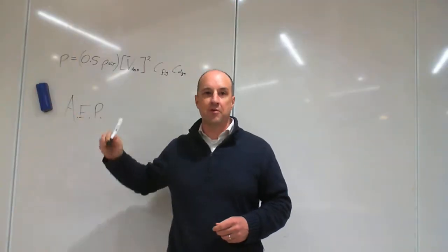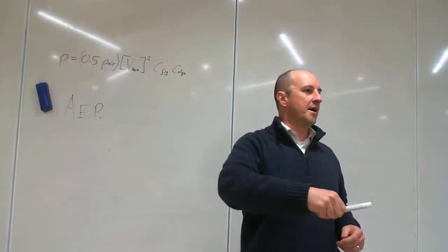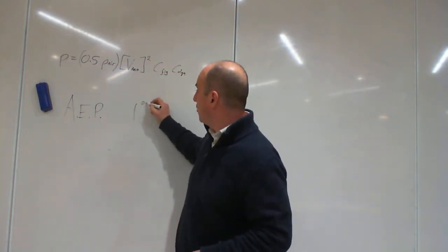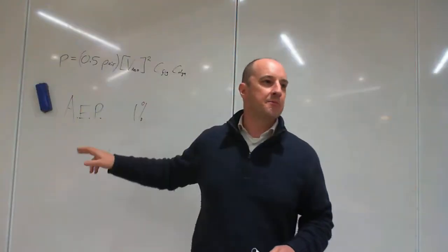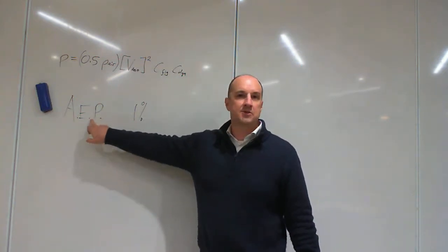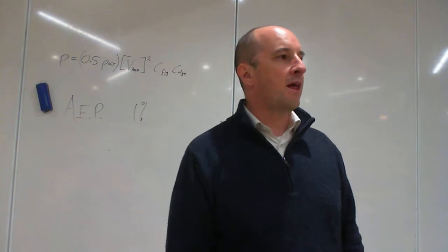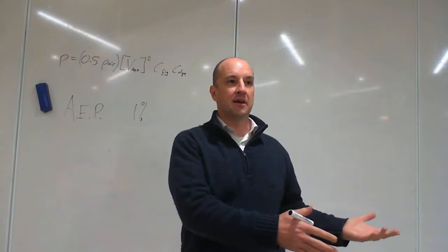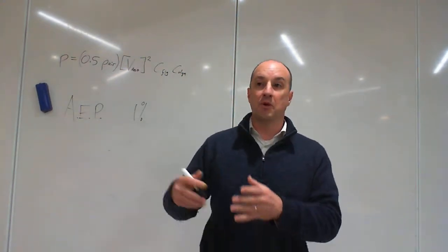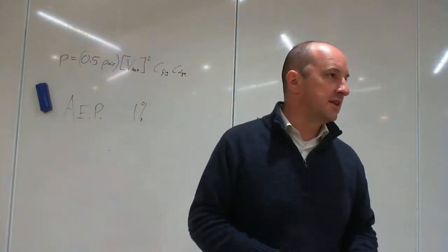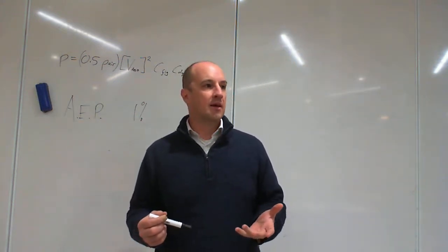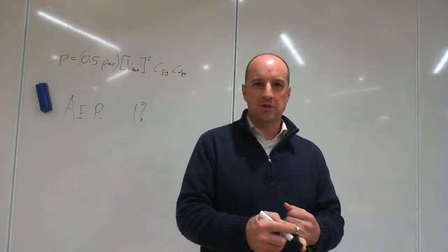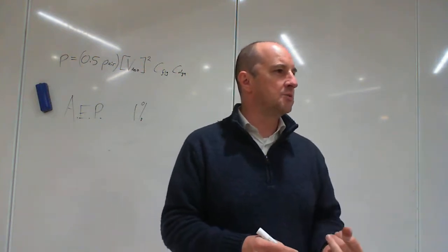Annual exceedance probability is the probability that the event we're talking about is going to happen in any one particular year. So if our annual exceedance probability is 1%, that means that this year there is a 1% chance of this storm occurring. Okay? There's a trade-off, obviously, between efficiency of design and how strong we're going to make this structure. So one of the things you need to do is consider what sort of structure it is. There's 4 categories. There's basically things which fall over and don't harm anybody, which is categorized as farm sheds. I would say a noise wall is one of those.